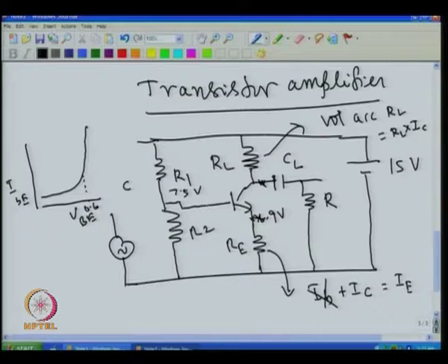So, what is the ideal voltage that I have to keep at the base? Now, I am taking the output voltage from the collector. The output voltage will be AC, that means the voltage will go up and then come down. If it is a sine wave, the voltage will go up and come down. So, if I want an equal swing, ideally keeping this at 7.5 is best. If I keep this at 7.5, then it can go up to 15 and also come down on the lower side. So, in the normal case without any AC signal, we try to keep it at 7.5.